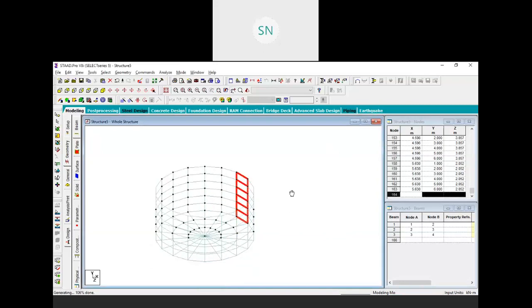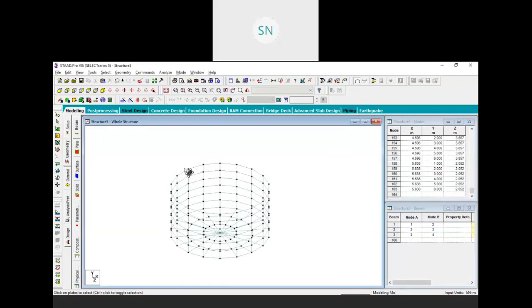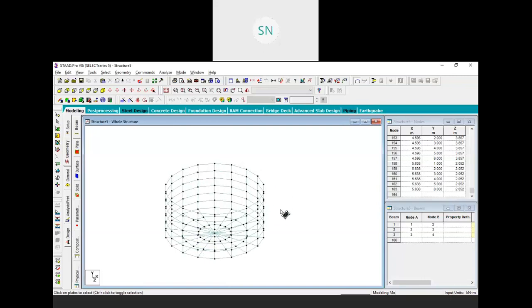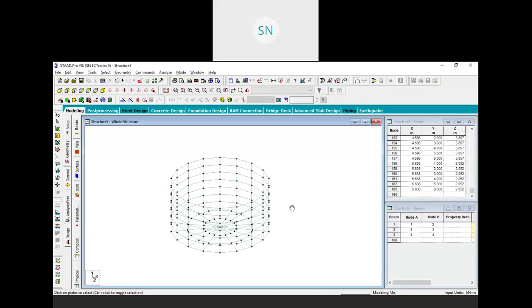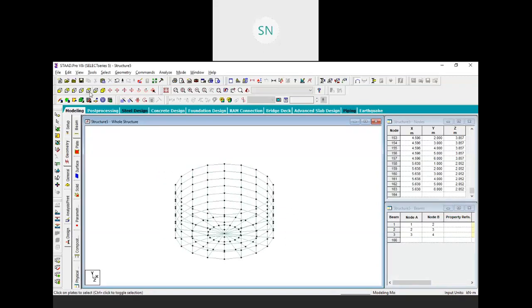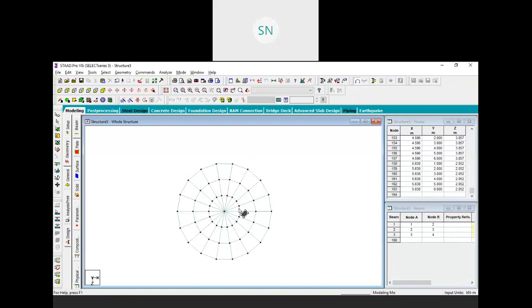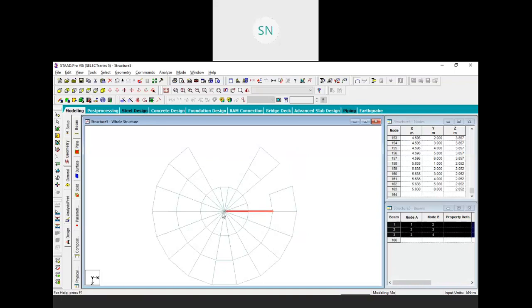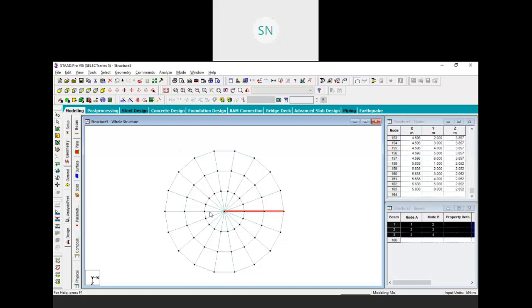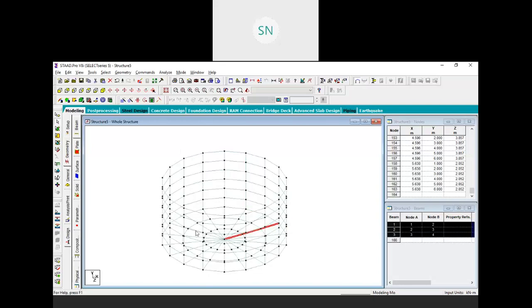Okay, so here we have a complete tank. It is clear for this tank. Now we need to create a support structure, right? So suppose for the support structure we will create beams first of all. So select your beam cursor and select it. So initially we have 3 beams over here. Actually I want to provide 6 beams for the support at the bottom, right? Here I need to provide 6 beams.